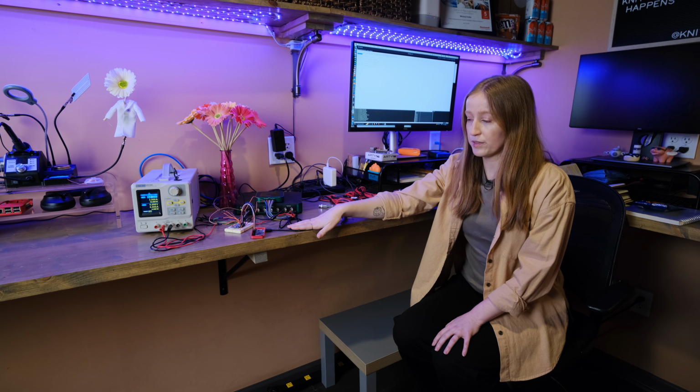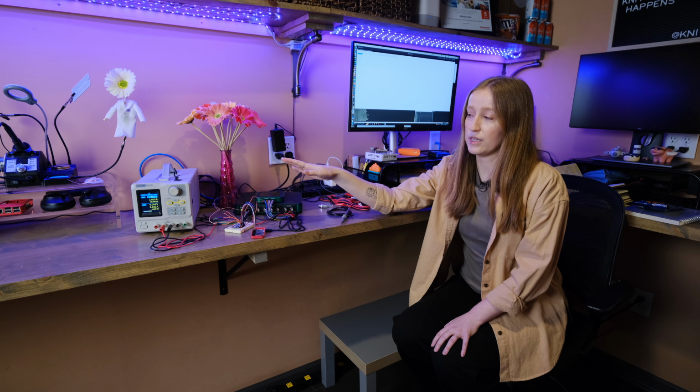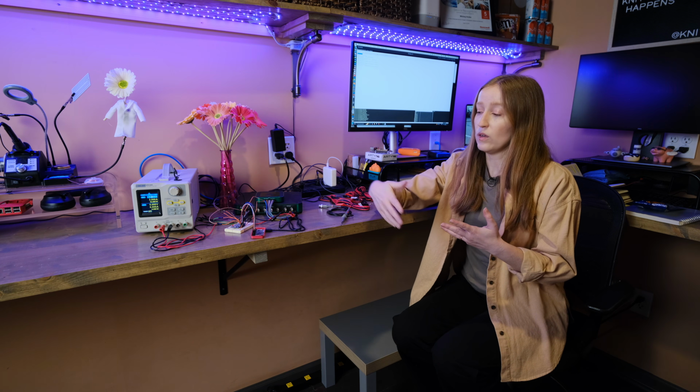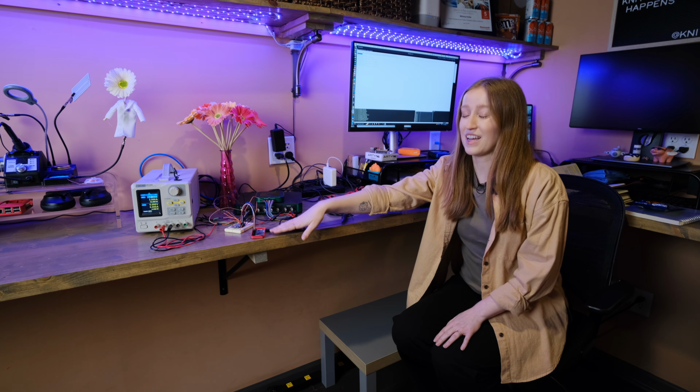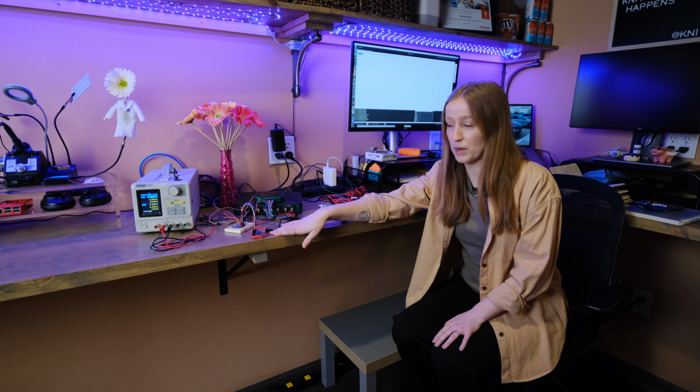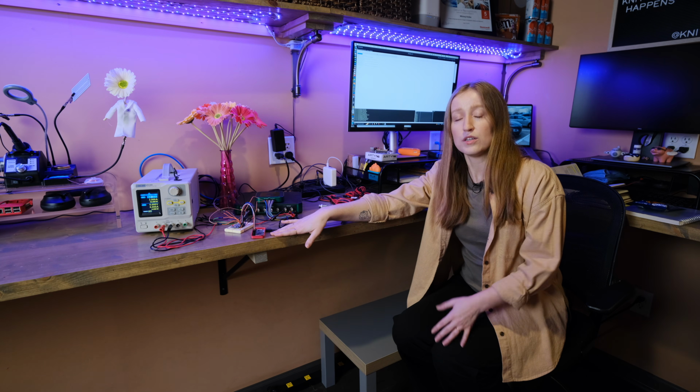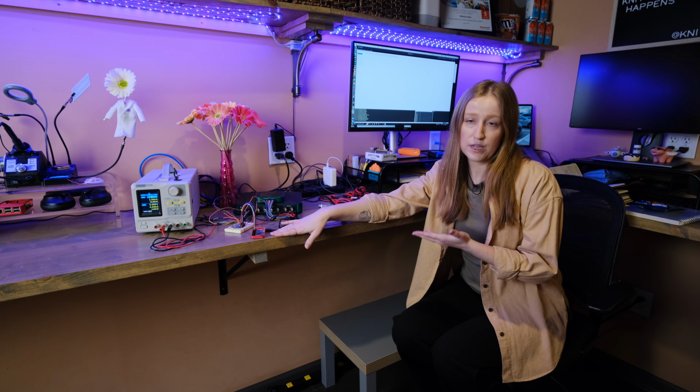And the last part of this setup is that the power supply is ultimately controlling the power going into the Raspberry Pi, which then powers the AD9850. Because the power supply is powering the Raspberry Pi Zero, I can monitor its current draw, which will tell me when the Raspberry Pi is fully booted up, when it's booted up its Wi-Fi chip, and when it's ready for me to SSH into it, which is how I'm controlling the Raspberry Pi Zero remotely. I have it configured so that I can SSH into it once it's booted up.